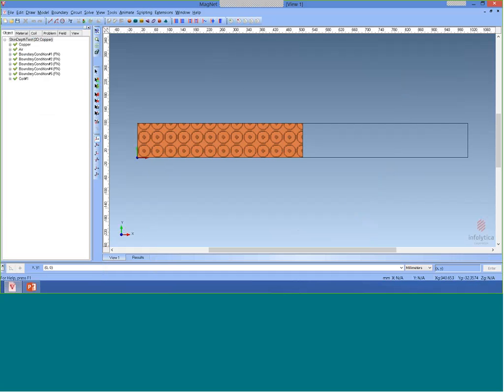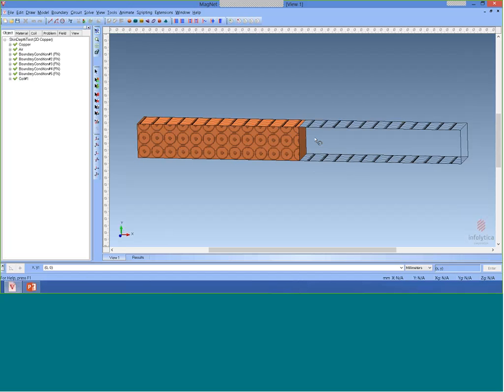So what I've done here to start off with is we'll start from our familiar skin depth type of calculation to see how we can handle the nonlinearity of the steel and how it's handled in MagNet. So here I have a 2D model that we can solve in both 2D and 3D, but in reality it is really a 1D model physically, because we've made sure that the top boundary and the bottom boundary here, that the flux will be normal to that.